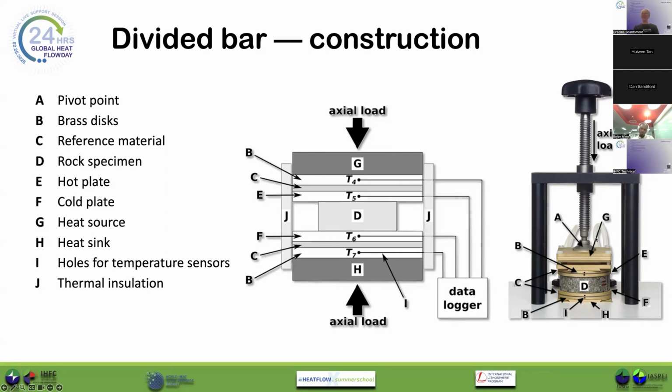So the other key features: we need to be able to apply a small retaining pressure along the sample to ensure good thermal contact. And we need to be able to measure temperature at 4 points throughout the thermal stack. So above and below the thermal standard at the top and above and below the thermal standard at the bottom, which also gives the temperature across the sample itself.